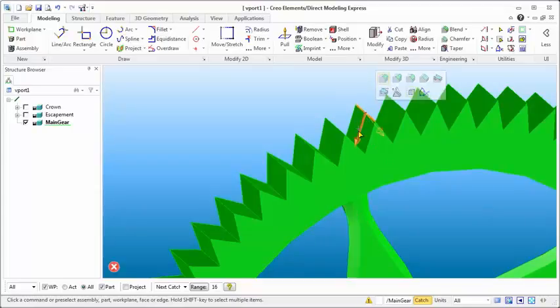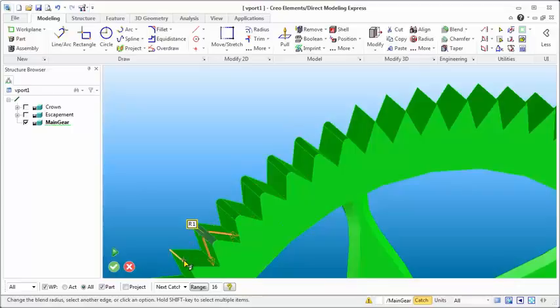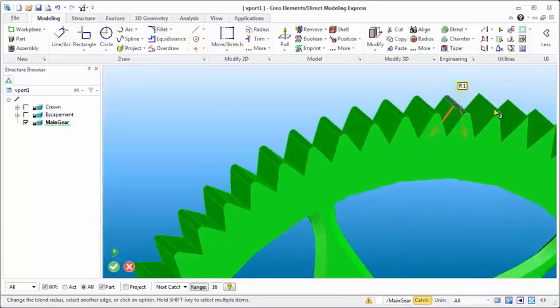So let's come in here, and I'm not a big fan of these being all that pointy, so let's make a radius of 1 on that guy. Come down to radius of 1. Now, as I select the edges, it's just going to start applying that radius to all these guys. So it can be a little arduous coming in and selecting all these points, because I did make 60 teeth, but it's worth it in the end. And we'll come through and round off all those gears, so that when you make something like this, it's a little more manufacturable and works a little better.